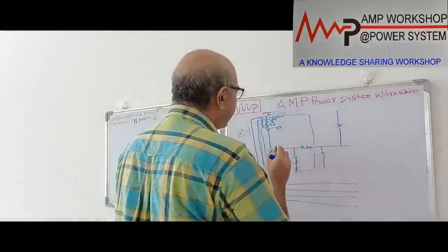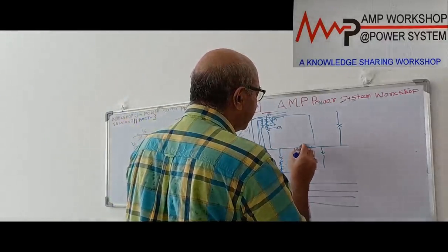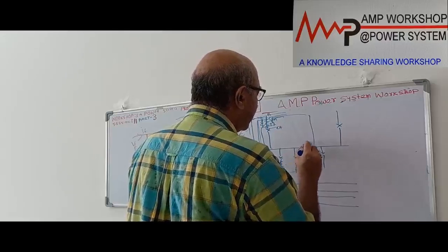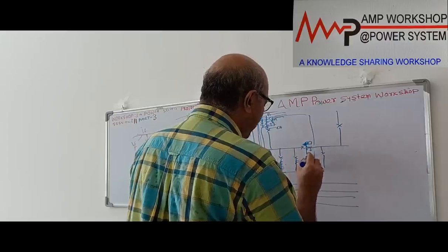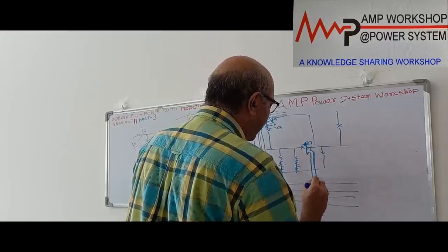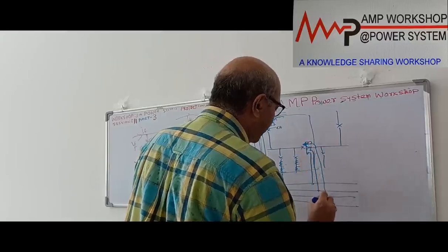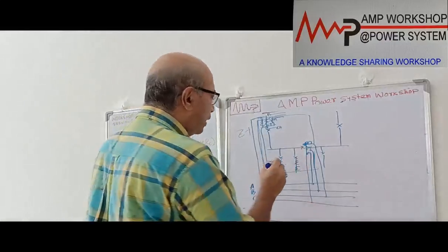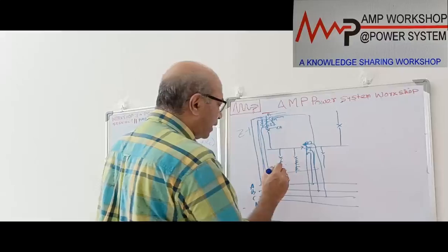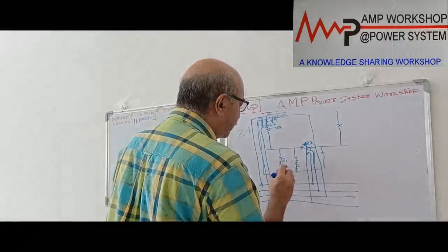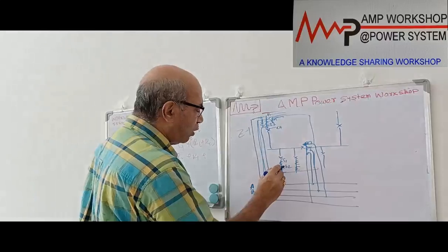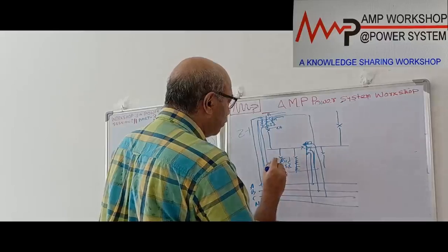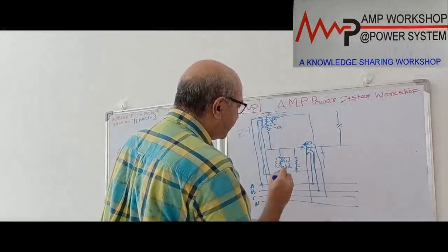And then similarly, for this bus coupler, this is your S1, current is coming this way, this is S1. Here also 3 CTs. These will be shorted, S2 will be shorted and S1 will be coming: A phase is here, B phase over here, C phase over here, and neutral will be connected over here. Similarly, this CT for the outgoing feeder, the current is going this way, this is S1 and this is S2. In this case, S2 will be connected and S1 will be shorted, and S2 will be coming to the A bus for all these CTs.